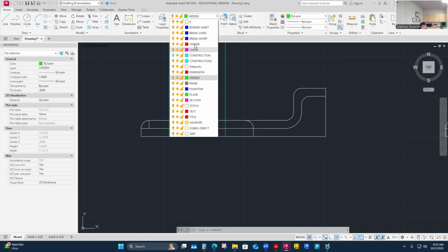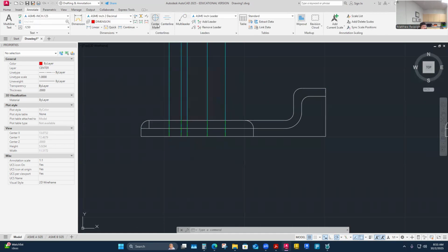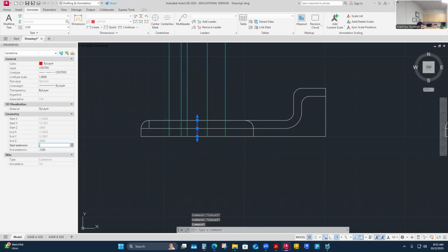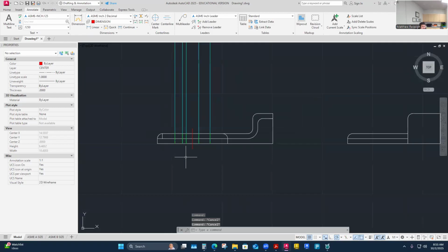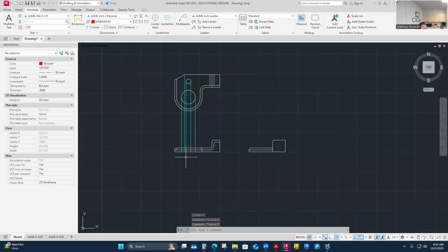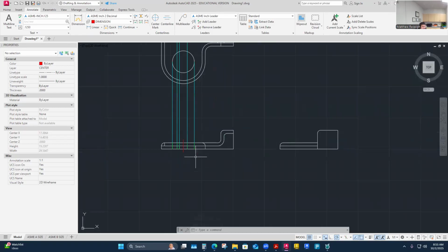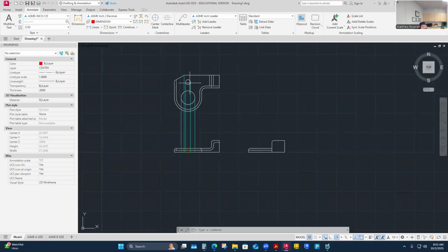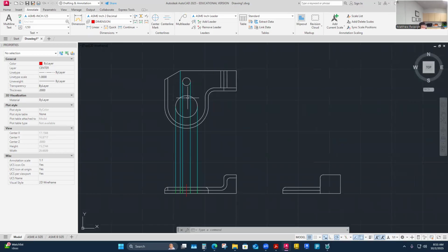And then maybe it'll help me if I jump over to center and put in a center line here while I'm thinking about that. I can use the outer ones. That's where my center line will go. Of course, it'll be 1/4 inch extensions. Yeah, and then anything hidden in my top view? I don't know if anything's really truly hidden other than, yeah, nothing.